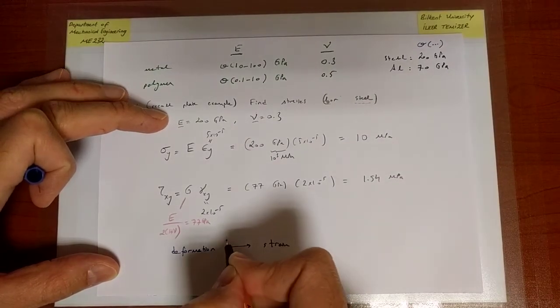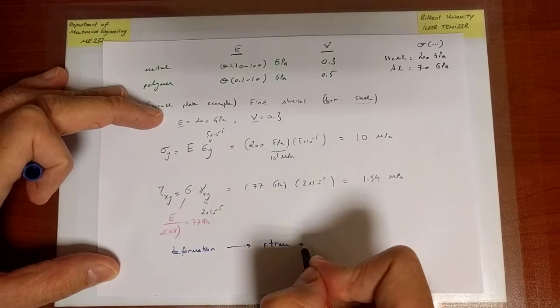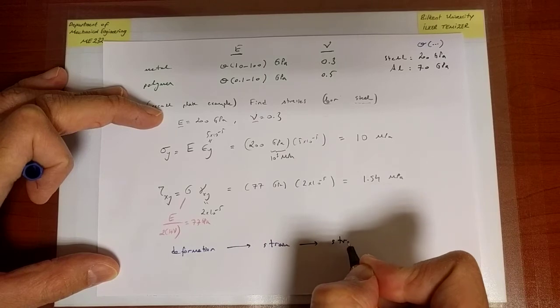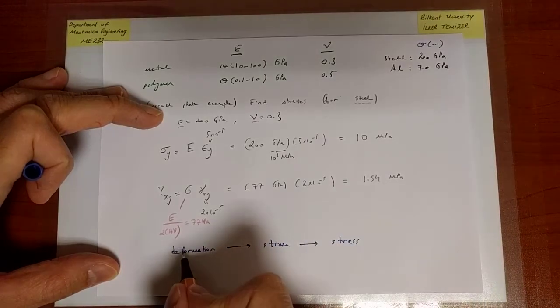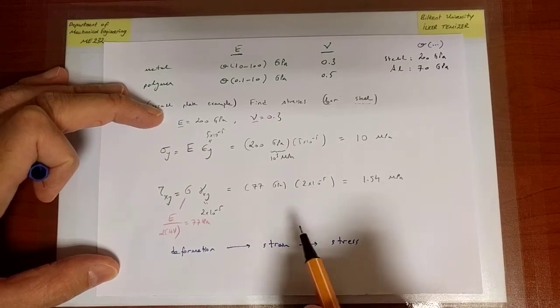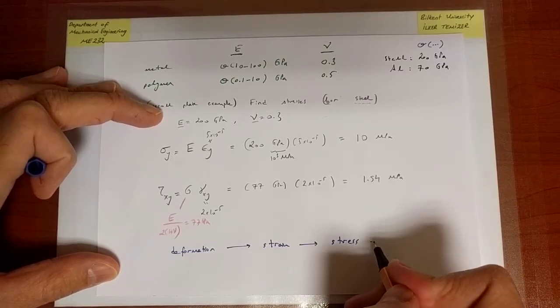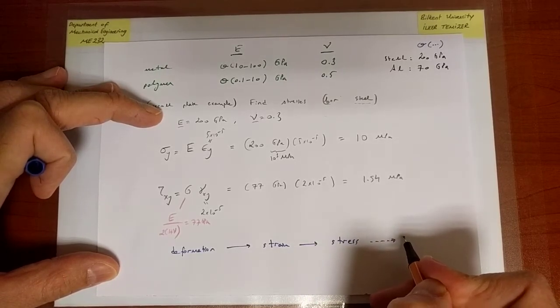This part has to do with the plate example, and now in the context of this particular example, from the strain we can go to stress. So we take ourselves all the way from deformation to stress, and if we're given some information about the geometry, we could multiply these with relevant area components and go towards a load if necessary.